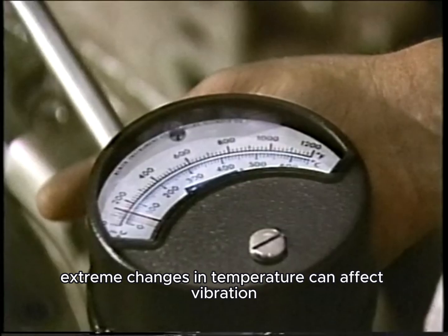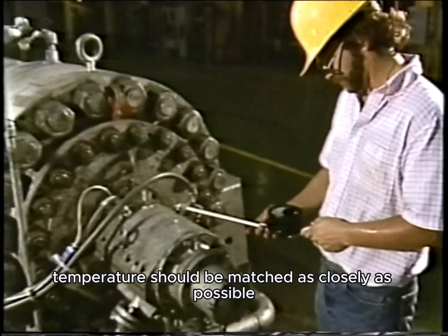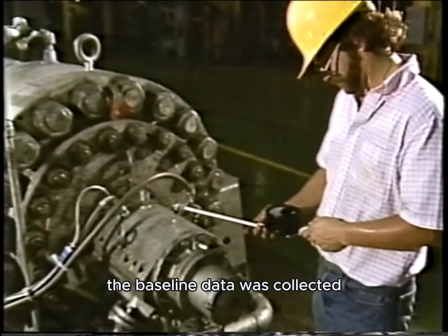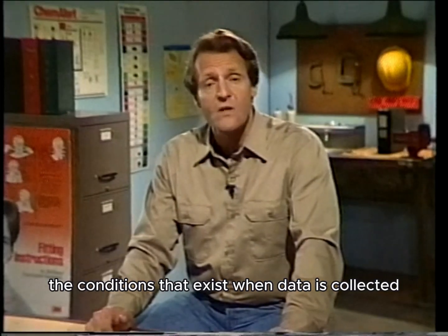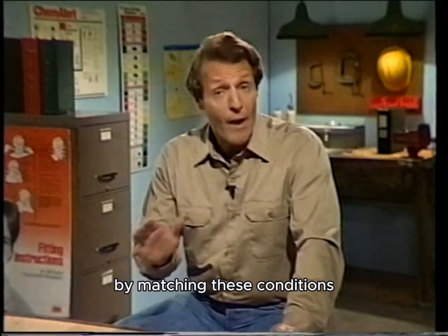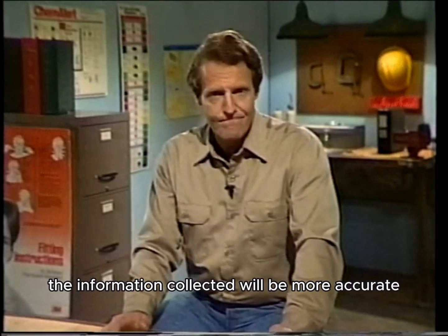Since extreme changes in temperature can affect vibration, temperatures should be matched as closely as possible to the conditions that were present when the baseline data was collected. It's important to record the conditions that exist when data is collected so that they can be matched for future readings. By matching these conditions, the information collected will be more accurate.